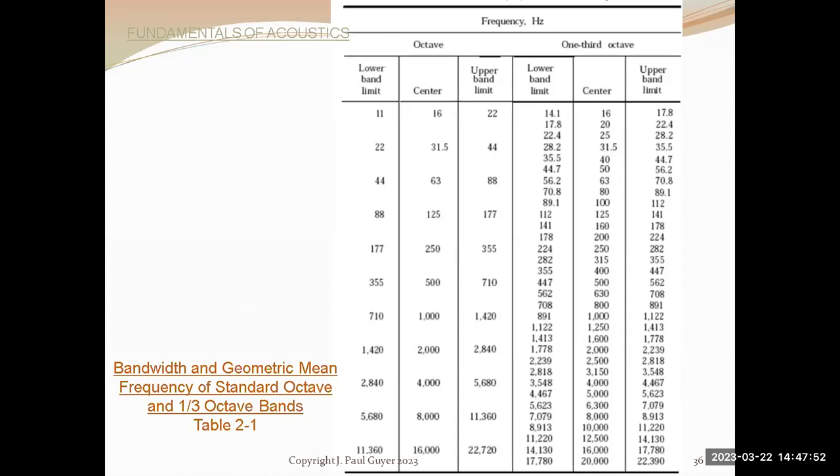These octave bands have been divided into what are called 1/3 octave bands, which is simply taking a given octave band and chopping it up into 3 parts. This is a representation of the frequencies that are perceivable by the young, healthy human ear.